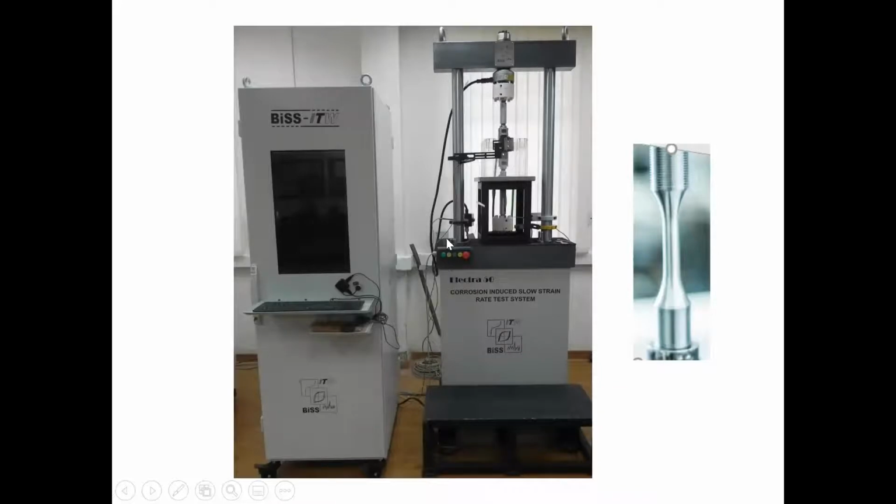And this part here and this part here is called a crosshead. This is the top crosshead and this is the bottom crosshead. And we have these vertical pillars. And the way this particular system works is that the top crosshead moves up and down on these pillars. And we have a load gauge here which measures the force. And in the box here, we have a gear mechanism and a hydraulic drive, which in this case pulls the crossheads apart. If you want to stretch the material in this direction, we need to make this go up relative to this. So we're pulling the specimen.